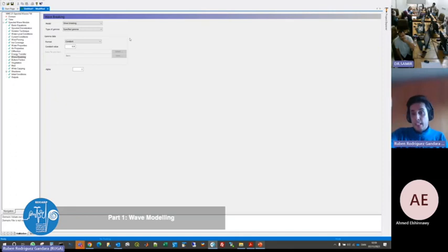And in there, in the different nodes or points, you can specify a different value of the gamma. For example, for one location, you can use 0.8, and for another one, you can use 0.72, because it represents better the breaking of the waves in that area than the other. But that is a map that you will have to construct yourself. It is not difficult, it is not rocket science, but you will have to create it yourself.